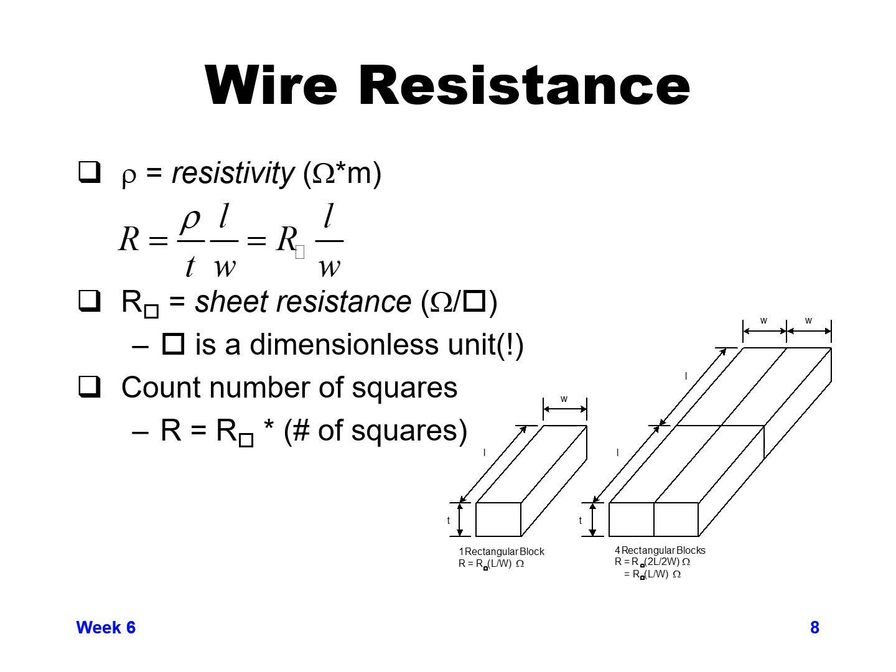And one of the things that's often done, because the thickness of your metal for a given metal layer is predetermined by the process technology you're using. So for a given wire that you draw in a given metal layer, you can't say, I want this wire to be thicker in metal 3 than a different wire that's in metal 3. All metal 3 wires are going to be the same thickness based on your process technology.